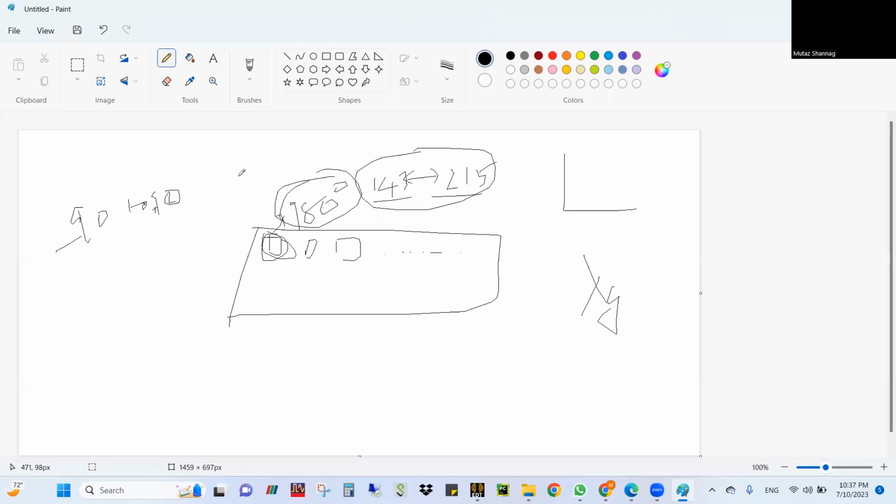For AMC, the artificial magnetic conductor phase. Yes. If you are varying from minus 90 to plus 90, you will not see a significant change in the performance of that particular AMC on the whole. That is why, in general, they have minus 45 to plus 45 and minus 90 to plus 90.